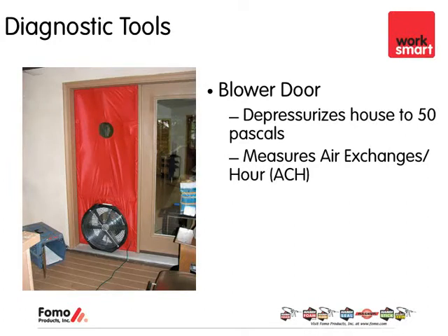And then what they can then do is measure your air exchanges per hour. The air exchanges per hour simply are how many times the air is completely replaced and replenished within a house on an hourly basis. This provides a measurement that a contractor can then use to determine how to address the problems within the home. They can measure after the work is done, and it provides validation for both the contractor and the homeowner that the work that has been done has actually reduced the air leakage within the home.